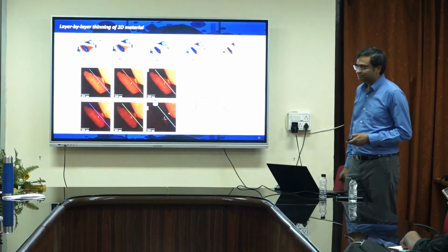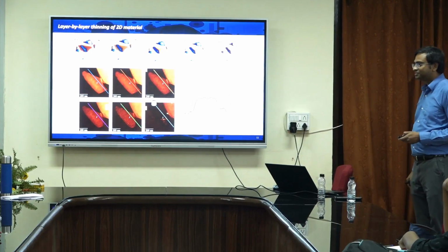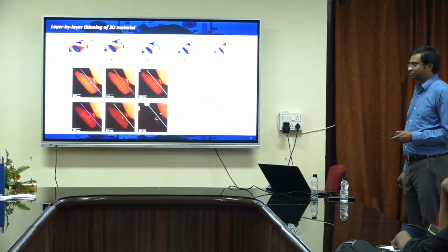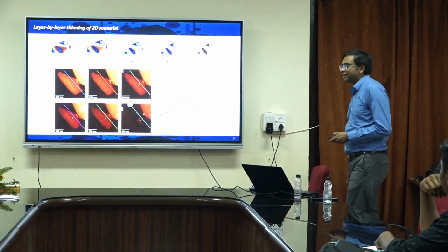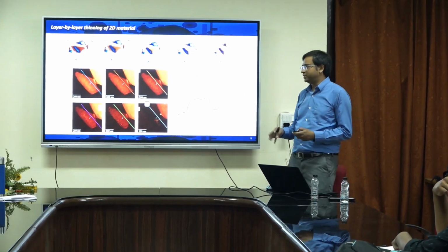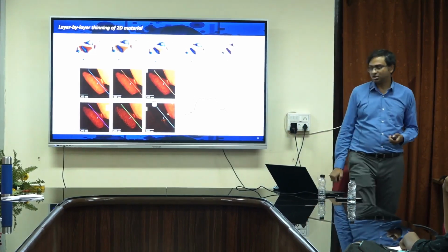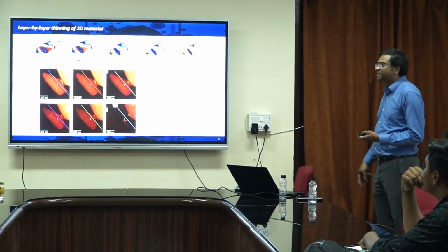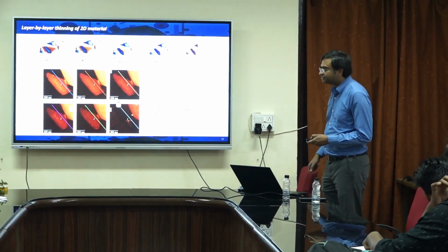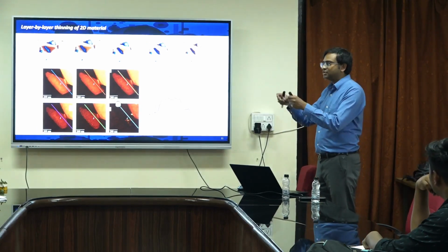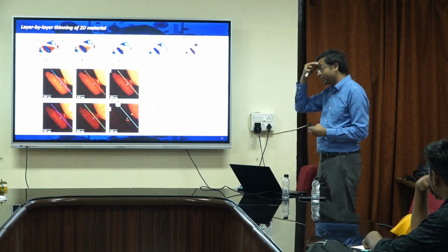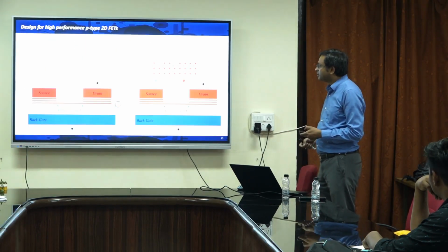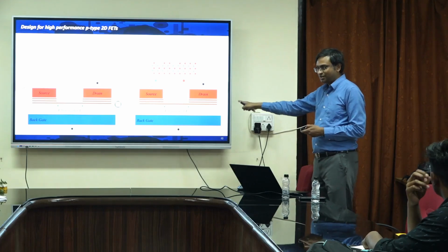Metal contacts are already there. No, no. This is a mild oxygen plasma, and these metals, we are using palladium and gold, they don't oxidize. And many metal oxides are also conductive. You can also protect the metal layers and then do the etching one by one, and that's what we are actually doing in this case. So we can now create this structure.